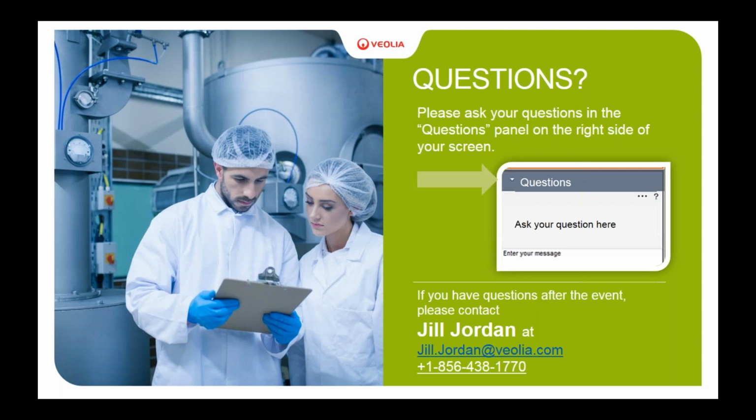But if you do end up having issues where you're not pumping as much as you think you should, or you see some crystals forming around, Jill, I haven't unplugged a whole lot of caustic lines in my life. How does that typically work? If it's still pumping and not totally blocked, sometimes running just water through it will clear it. If it's really clogged and you can't push anything through it, I have to say, unfortunately, the best way to do it is to cut it and replace it.